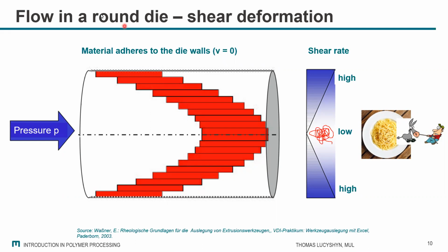And what is happening in this area is, imagine you have a polymer molecule which is oriented in this way. Now in this layer, the speed is higher than in this layer. So the part with the higher speed orients the molecule in this direction, because it is moved faster. In the end, the molecule gets oriented in the flow direction. So in general, in those layers close to the surface, the molecules are getting oriented and also a little bit disentangled.